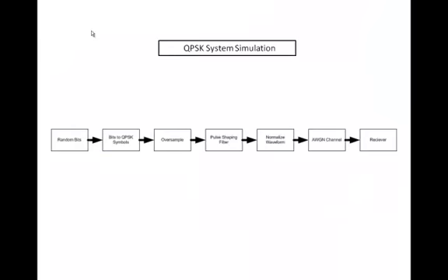Okay, so for the QPSK system, I was able to read in a proprietary bit stream, a file, and go through my process and generate an IQ waveform that was played back on an RF up converter, an RF signal generator, fed into a receiver, and it played audio. These are the steps that I took.